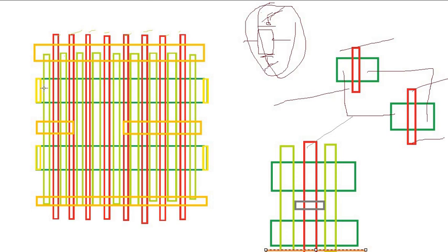If you want this connection to go above, for example, you can just deactivate this or pull this cut MD layer inside, and this MD layer will go above. You can connect it to the neighboring devices you have placed on the top. Same thing implies: you can just add the cut layers and maneuver the connections the way you want. So whenever you are using any cut layer, the connection becomes different. This net has a different connectivity, this net has a different connectivity. Let me take another example and try to explain.